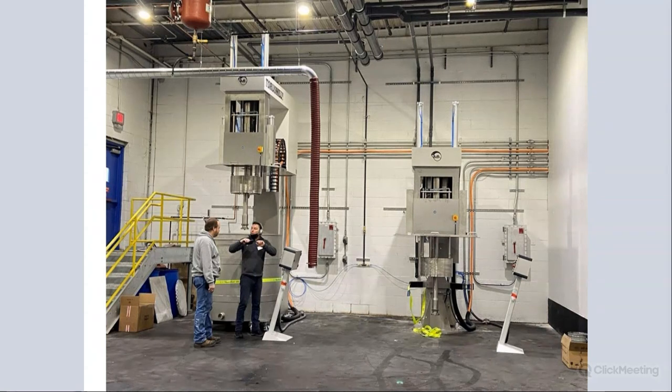Here you can see actually 2 production scale Dispermats, and they are really cool. And what they are is basically a combination system, disperser slash basket mill all in one. The cowl's blade or the impeller blade is behind the gentleman with the gray sweater leaning against the blue drum. So they're not installed yet. But basically what happens is we first pre-disperse with the blade. That always stays on there, so don't take that off.